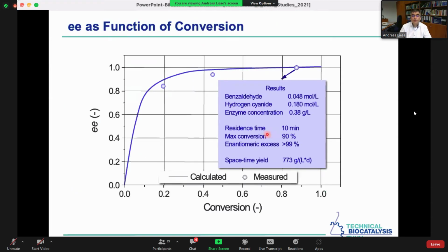Therefore, if we run such a reaction, with enzyme-catalyzed product formation and a racemic non-catalyzed reaction going in parallel, the right reactor for selection would be the CSTR, but we have to watch out for the conversion we establish and closely control the residence time.